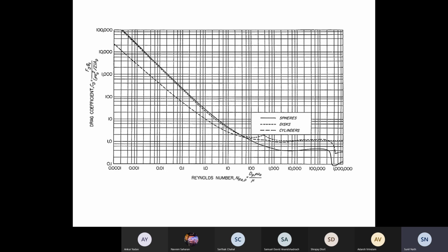Then we said, well, let us look at how this CD, which is there, because all the hydrodynamics was not included, it was there in that CD. And we said, let's look at how that changes with the Reynolds number. We did that for the Stokes region. We did that for Newton's region. And you got exact relationships for the terminal velocity, the CD, and the drag force. Okay, so six equations. Now I want you to do the same for the intermediate region, but this one is just one step further. You have to use your gray cells.